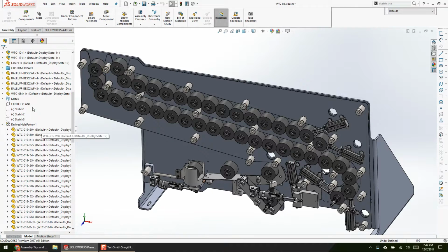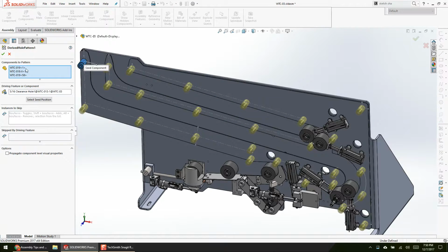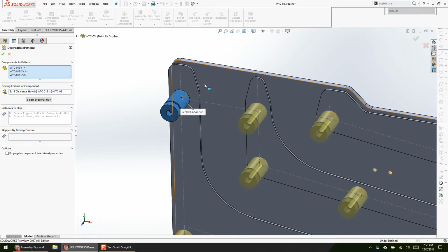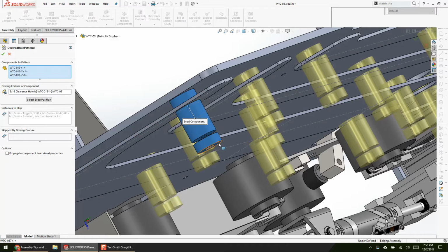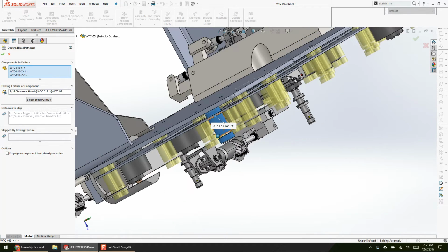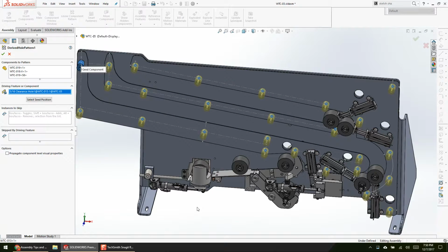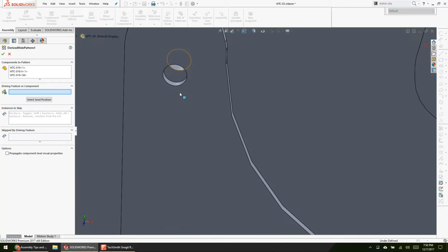But in this instance, I can do a magical component-driven pattern, or pattern-driven component pattern, whatever that's called. And so I picked all 3 of these, the spacer, the component, and the spacer, because there's multiple pieces of steel here. Picked that whole pattern, which we can see highlighted in blue here, and patterned it all around. Where'd you pick the whole pattern? How do you... Just through the graphics view. I'll just pick one of them?